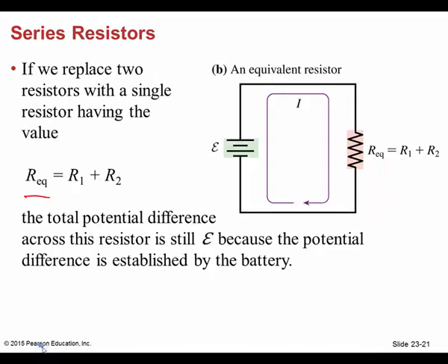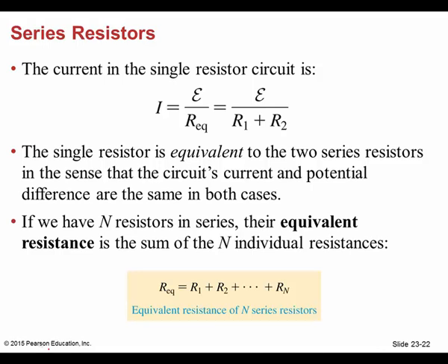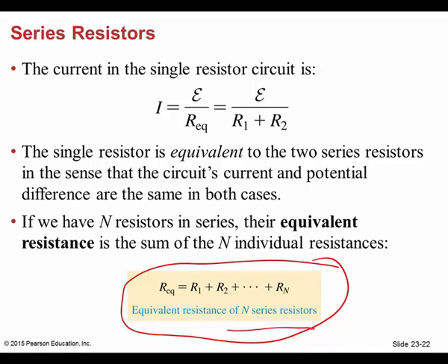All right, so there's your resistors, and of course here we're talking about the current. The current, regardless of how many resistors you have, will be the same on every resistor, even if you have a 1,000 ohm and a 1 ohm in series. So we have what is called the equivalent resistance. There's another equation for resistors in series. Now this is for series, okay?